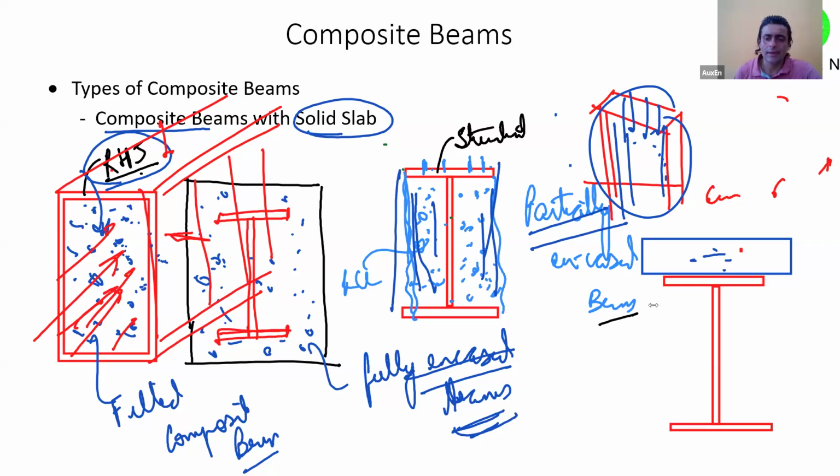Dr. Saab, Vinu Bhai Saab, is saying it can be filled with self-compacting concrete. Yes, sir, it can be filled, but then you will not be able to ascertain whether the concrete has been filled properly or there have been some honeycombs left, or how well it has reached all the places and corners. We will not be able to ascertain that, especially if your spans are, let's say, a 5-6 meter beam span and you were to fill it from the starting and ending. I don't think you will be able to ascertain the adequacy of filling or how well it has been filled.